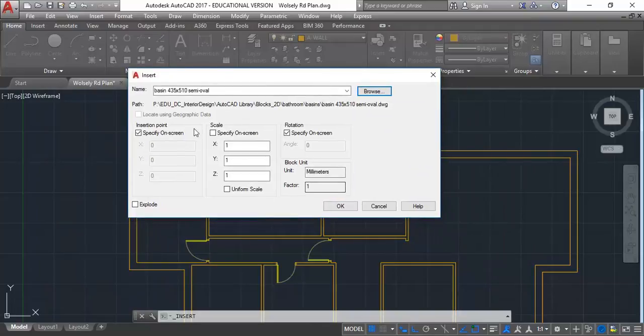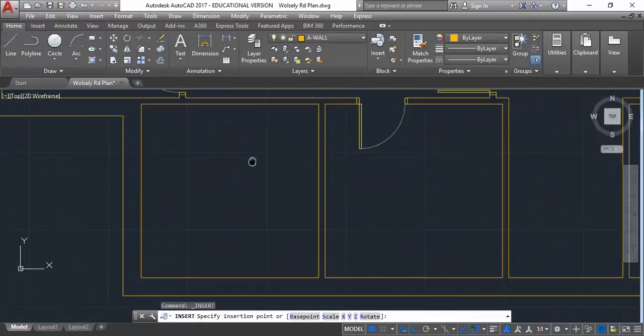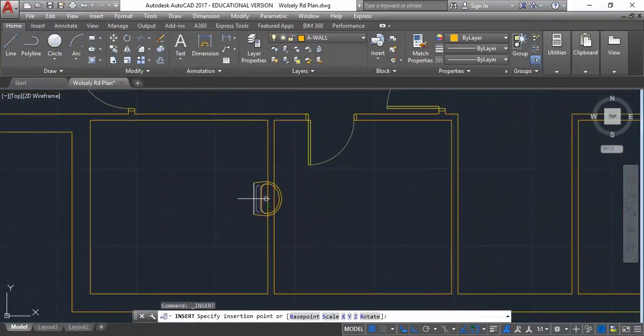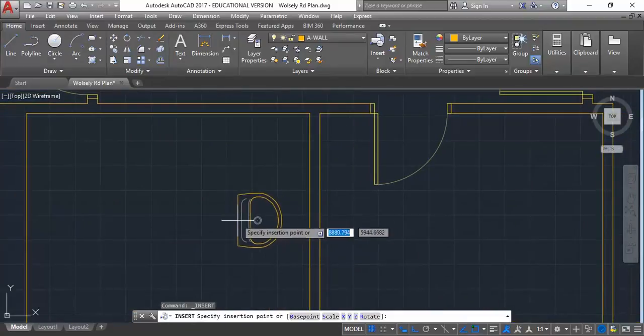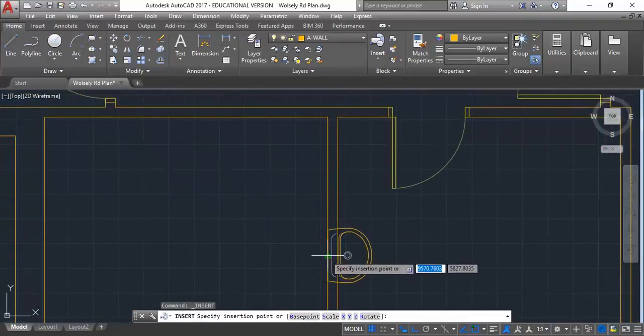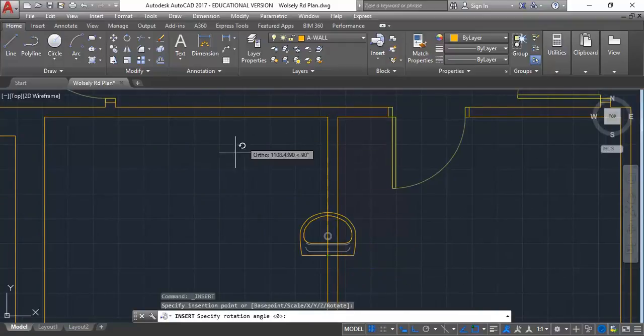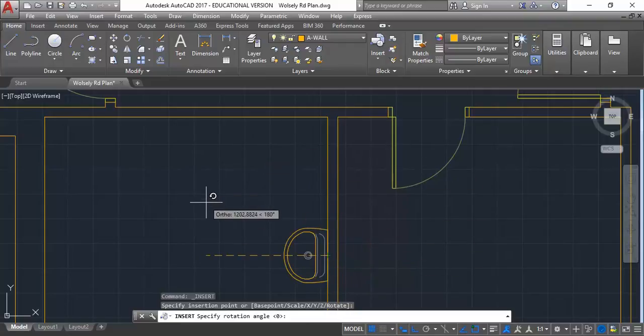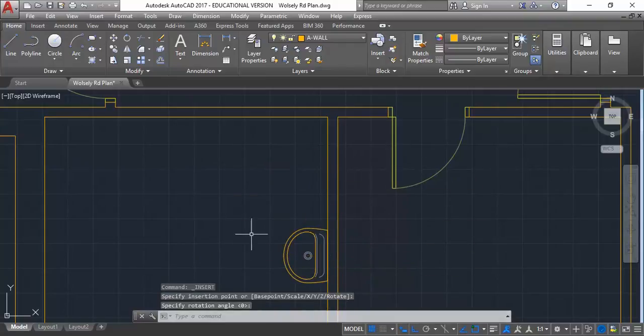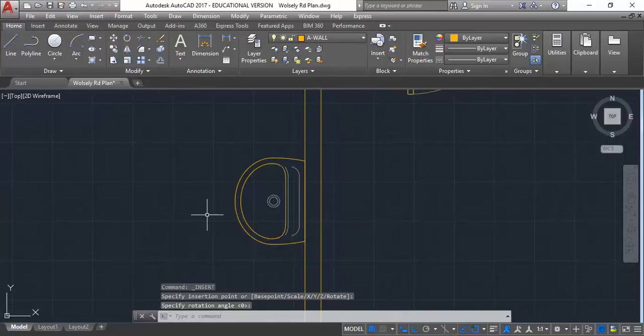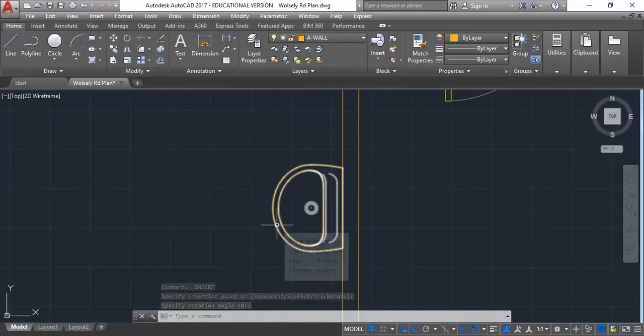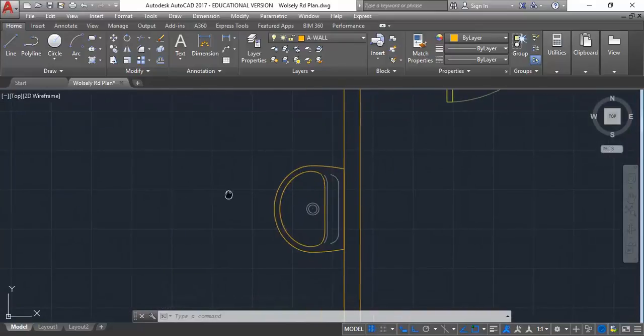Okay, so again, just the insertion point and rotation options turned on. Click OK. So I'm going to choose a point. Now, there it's snapping to the midpoint. That's okay, I can move it afterwards. So I'm just going to snap, and then using the cursor, get the angle I want. Click.